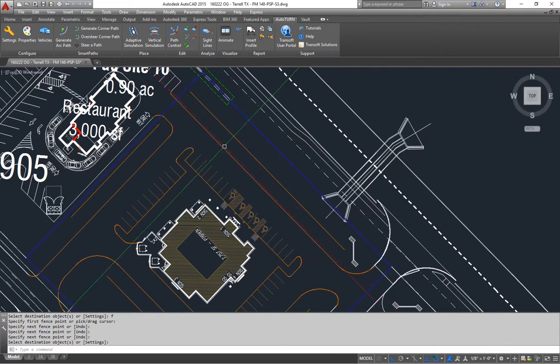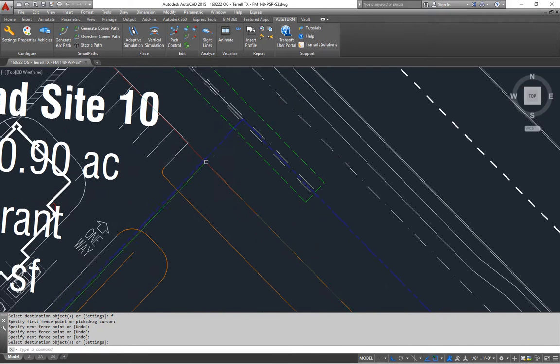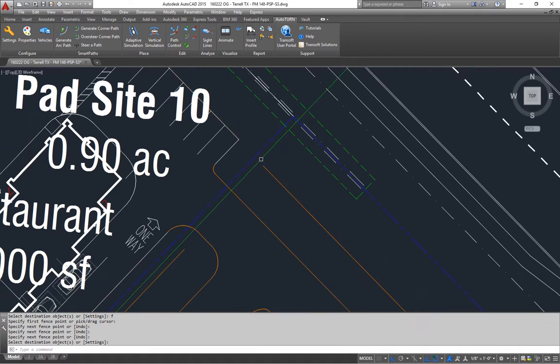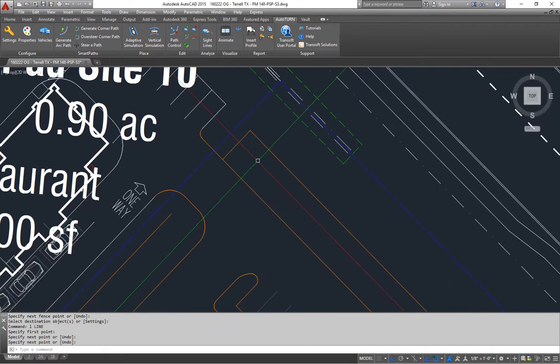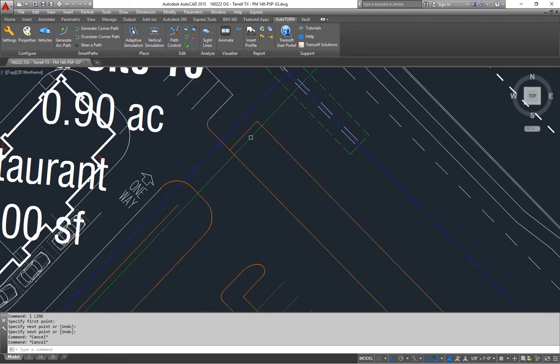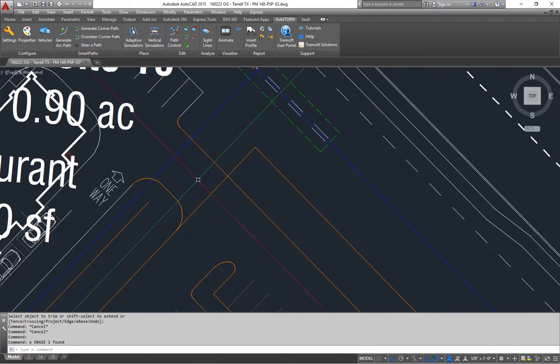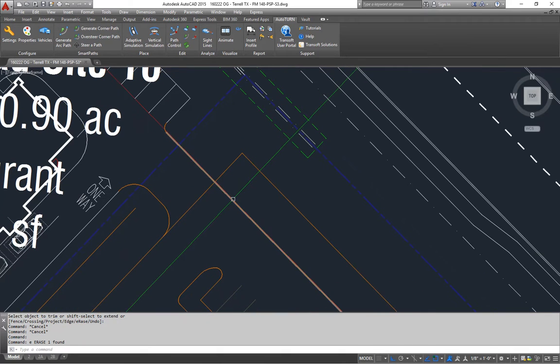Now back in here, let's start up here, because I offset this 5'6", if you remember, so that I would have a 6-inch curb and then 5 foot of green space. So in order to maintain that, actually, you know what? I'm rethinking that. Since this is sort of like an entry drive, it's cross access, I'm going to start this parking from back at here, kind of like I did the other ones, so that we're maintaining kind of a driveway here.